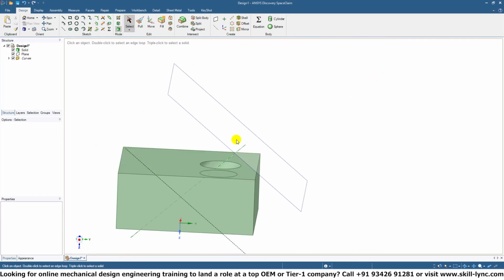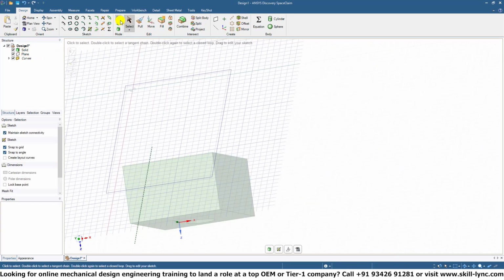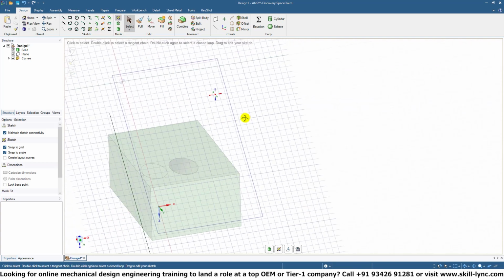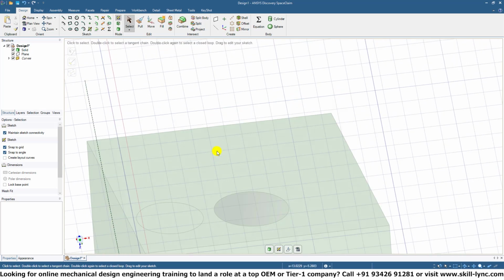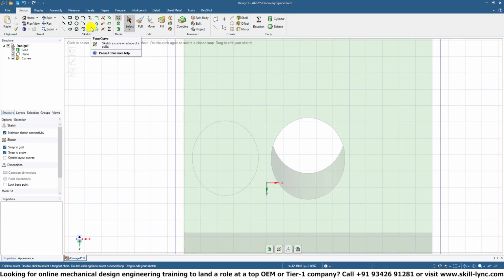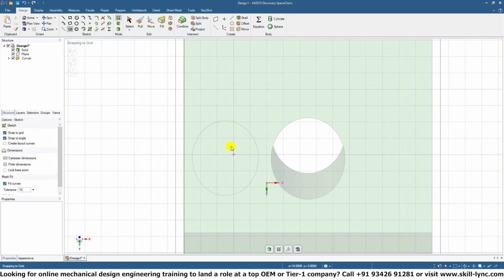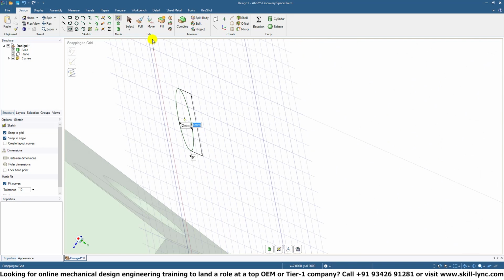Okay, let's delete that plane. Let's select this plane here. Now, hopefully when we select sketch, yeah, there we go. Now the sketch plane is angled. So let's go back and select our little ellipse tool. Let's try it again. Let's say we wanted to do it like that, 2 millimeters by 4 millimeters.